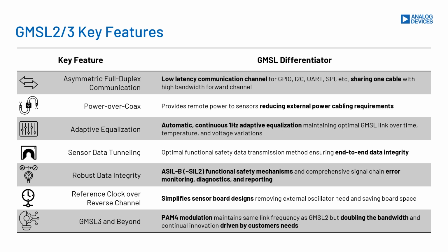This helps remove an external oscillator for both the serializer and the image sensor to further reduce the BOM cost and to shrink the board space. When using multiple sensors in aggregation mode, this will also guarantee the drift of all reference clocks are moving in the same direction.